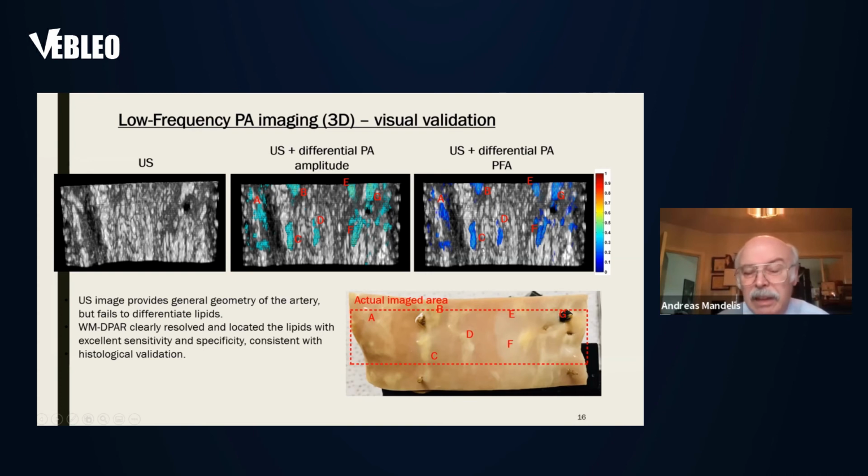And again, this is actually quite nice because we're only using up to 4 megahertz of sound. So usually in cardiology, in clinical practice, the ultrasonic transducer is up to 40 megahertz in order to be able to see this kind of resolution. But the resolution that you get from the light and the confinement of the absorber, it's almost as if you had a higher frequency transducer operating under this lower frequency instrumentation, which is absolutely marvelous because this is exactly where we want to be.